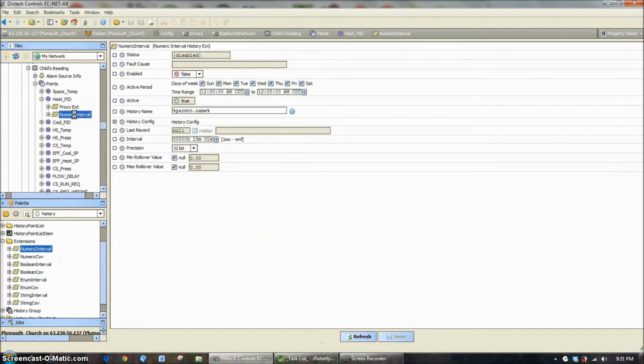Now we'll just double click it. I'm going to write down in history name. There's two ways you can do this, and I've touched on this in other videos before, but depending on how you want it to be named, in this case I'm going to be a little bit fancier with it. Parent.name is referring to the parent of this extension, so the parent would be heat PID. So when we looked in our history chart, we would be finding a point that says heat PID. Well, that's not overly useful when you have a whole bunch of heating PIDs in a building.